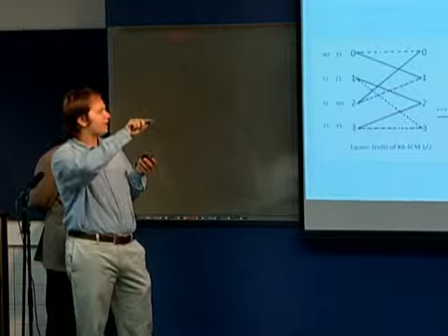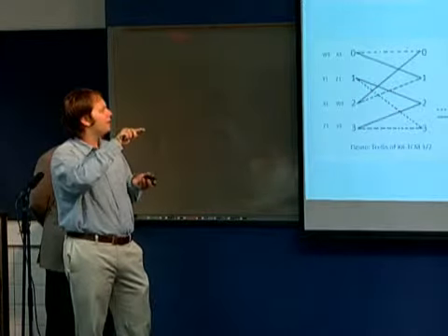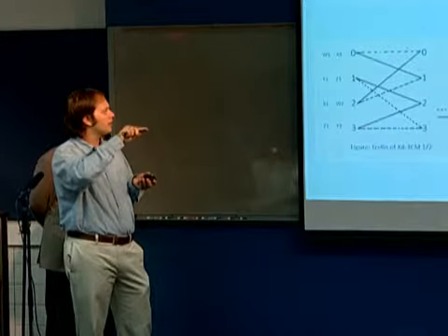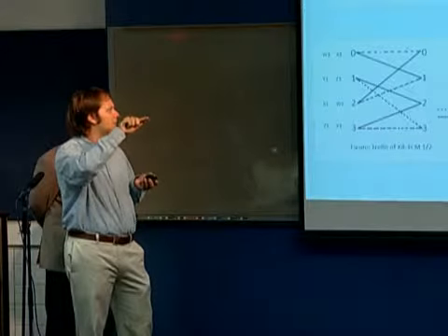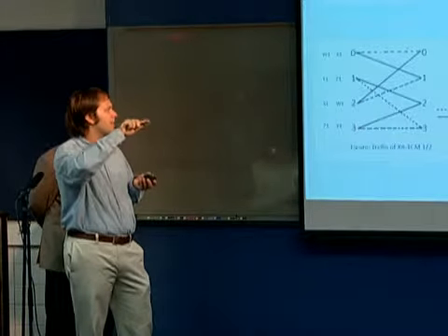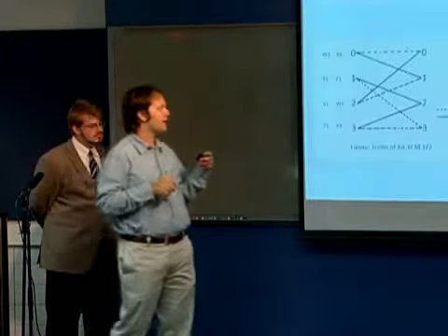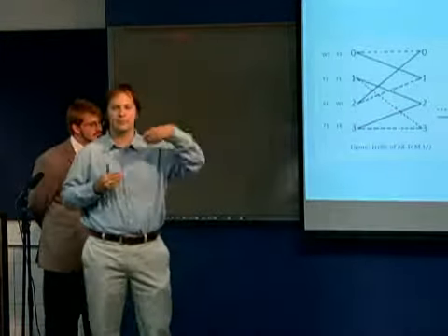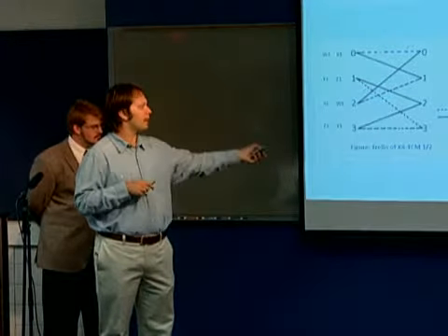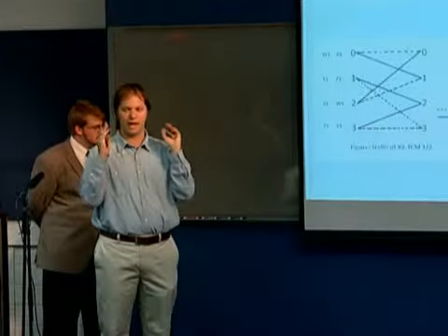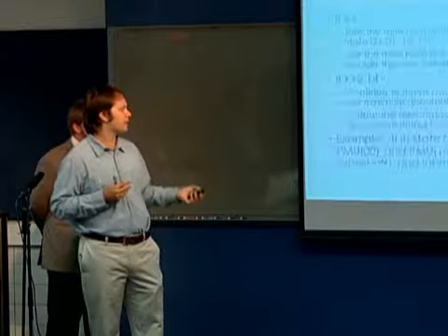So for here we take the minimum of this plus R, this transition plus U, this transition plus T, this transition plus V. So that is how we accumulate what is known as our path metric unit. And we add these together, and then once we have 14 of them, according to our constraint length, we're going to go to the next part of the process.